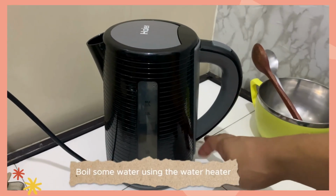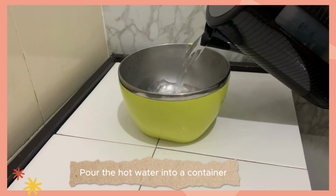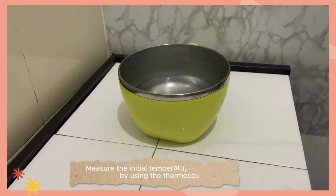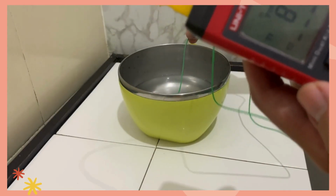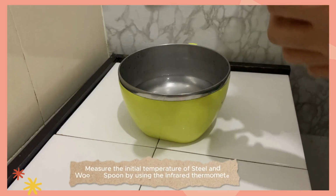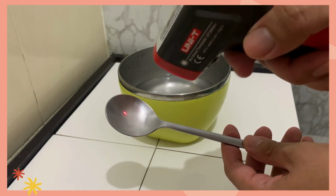Boil some water using the water heater. Pour the hot water into a container. Measure the initial temperature of the hot water by using the thermocouple. Measure the initial temperature of the steel and wooden spoon by using the infrared thermometer.